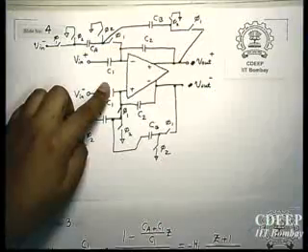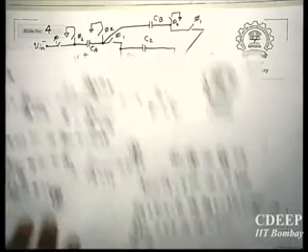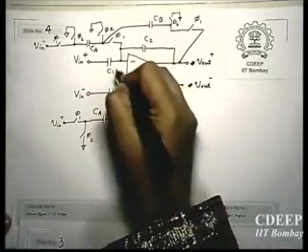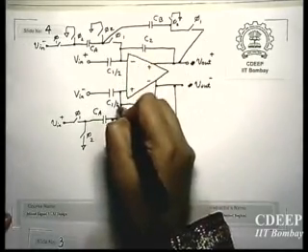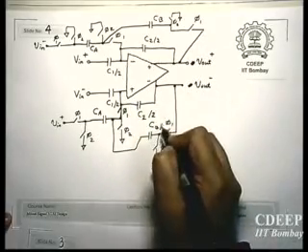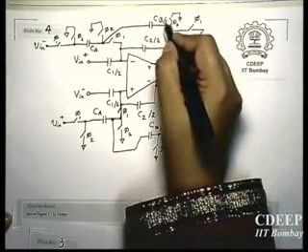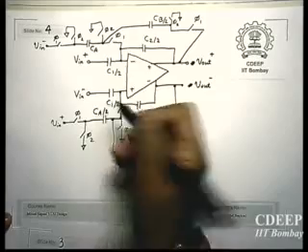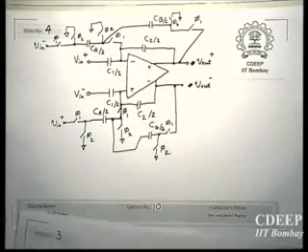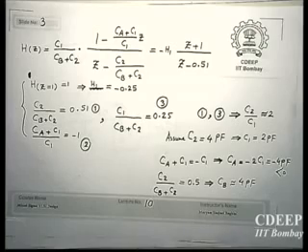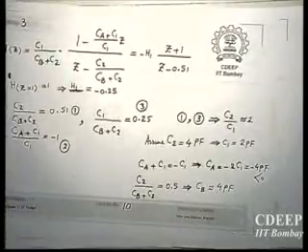So instead of C1, which was for example 2 picofarad, you can use 1 picofarad capacitors here. Therefore, you can just divide them by 2. This means that instead of using C2 as 4 picofarad, you consider 2 picofarad for the differential architecture. All values will get scaled by a factor of 2.